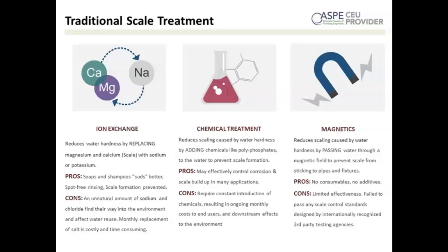And it's also got a lot of wastewater, which impacts the environment and causes downstream issues with municipalities that have to treat the water that has heavy sodium content. And then just the maintenance aspects of ion exchange, with the salt being replenished and labor associated with that and proper dosing. And so it's just a much more intensive maintenance requirement.